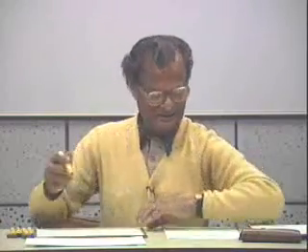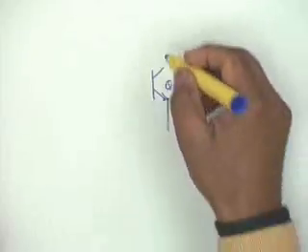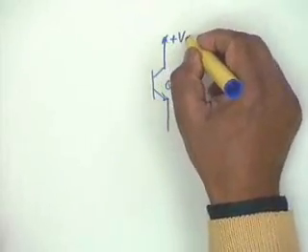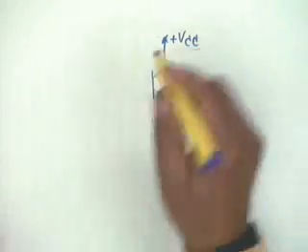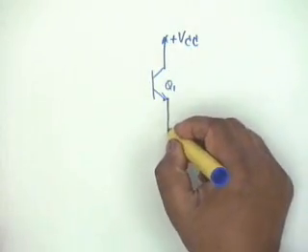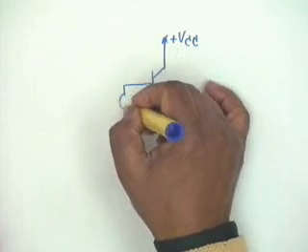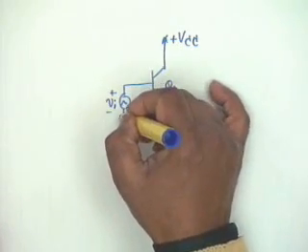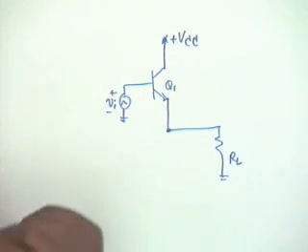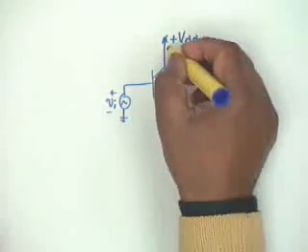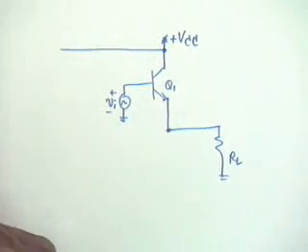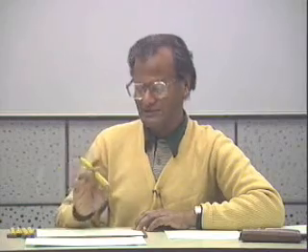Okay? Right. Now, about this circuit, I'll draw this circuit and then I'll quit for the next class. Q1, it is operated as an emitter follower, and therefore the load RL is from here to ground, and normally you expect Vi from here. The biasing of the transistor is done by a current mirror. Now you no longer require a PNP current mirror. You can do it NPN, and if you can do it NPN, you should do it NPN, because PNP has its own problems.